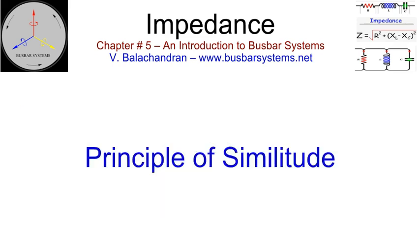Principle of similitude. When it is expensive to test a full-scale model to evaluate the resistance, inductance, voltage drop, and power loss, it makes sense to scale down the model. Consider two round conductors of radius a, separated by a center distance d, having a resistance R and an inductance L. If all the dimensions are halved, to a/2 and d/2, the resistance will become 4 times R, while the inductance will remain L.